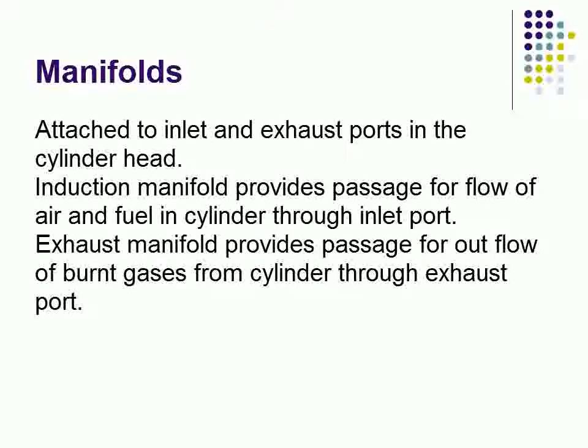The next components of an IC engine are the manifolds attached to inlet and exhaust ports in the cylinder head. The induction or the inlet manifold provides passage for flow of air and fuel in cylinder through inlet port, whereas exhaust manifold provides passage for outflow of burnt gases from cylinder through the exhaust port.